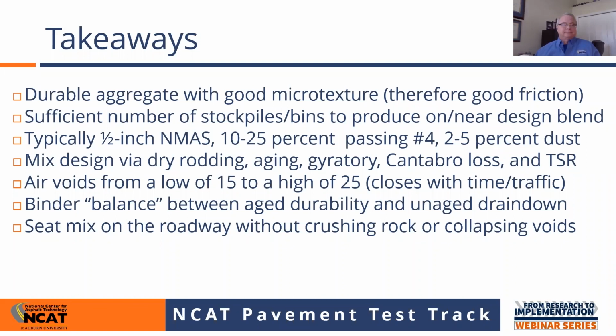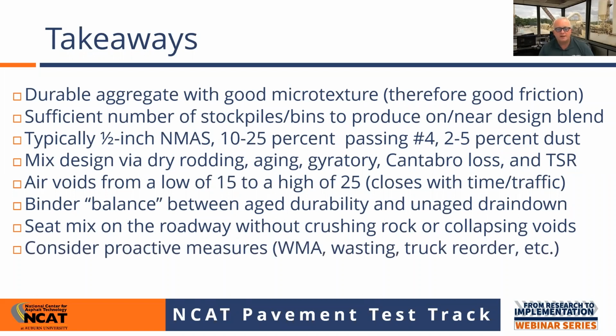All right, good deal. So when you put this mix on the road, you don't really want to compact it. You really want to seat it on the roadway without crushing any rock and collapsing any voids. One of our challenges is we're placing this mix, which we typically use on interstates, on high-speed roadways. We're doing more and more of that work at night, so there's less that you can see. You're more concerned about traffic hazards on these busy roads. So we really have got to make sure that we're not over compacting these mixes, because I think that has been a challenge with some agencies.